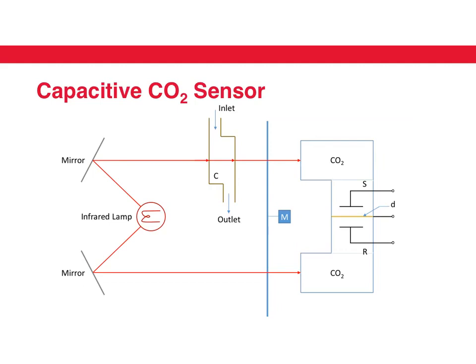So this is a very interesting example of how, starting from a differential capacitor, you can make a reasonably complicated carbon dioxide sensor. Of course, you do not want the infrared light to fall on these chambers for a very long duration of time, because the temperatures would rise very high. Therefore, there is this motor here which makes sure that the infrared light only falls very intermittently on these chambers. And over a long period of time, the pressure between these two chambers equalizes, because there is a small hole in the diaphragm that allows such equalization to happen.